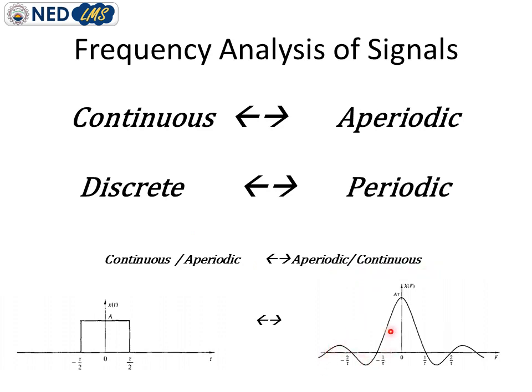And you can see that your spectrum is continuous, and you do not use dotted lines here, rather you have used the solid line. So the continuous and aperiodic time domain representation will always result in an aperiodic and continuous frequency domain representation. So you can try different combinations and come up with the actual idea of the frequency domain representation.